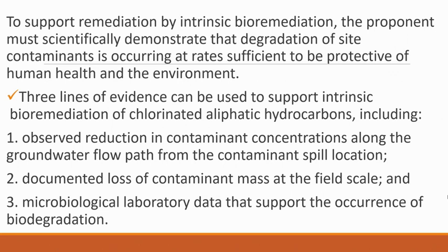These include: one, you observe reduction of contaminant concentration along the groundwater path from the contaminated soil location. Two, document loss of contaminant mass at the field scale, and three, microbial laboratory data that supports the occurrence of bioremediation or biodegradation.